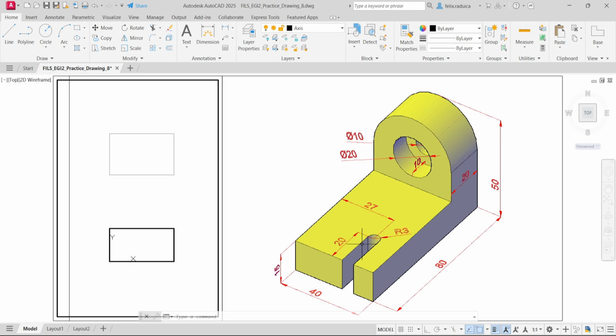And to do that, we'll have to draw an axis line which is 23, 26, and 29 millimeters, starting from outside here with the 3 millimeters outside. So give the line command. Remember, we have 3 millimeters outside, so minus 3, and the Y is 13.